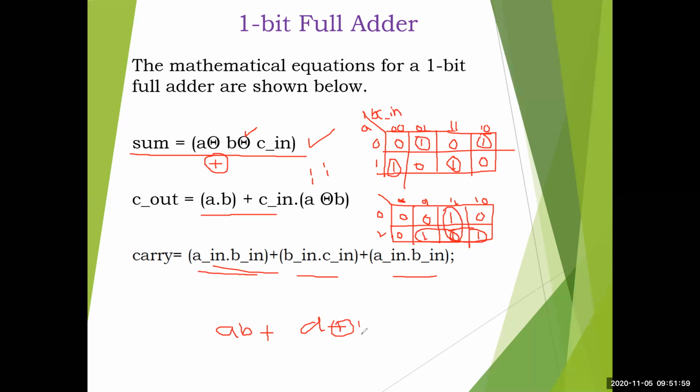So this is like using two half adders' output. A full adder can be constructed using two half adders and an OR gate, as you have studied, right? So that output is coming here, and that is what we are using. This is the output with respect to your sum and C out; use the same notations we have used. I have shown you this additional carry because you will also get it, but I am not using it in this example. Hope it is clear.